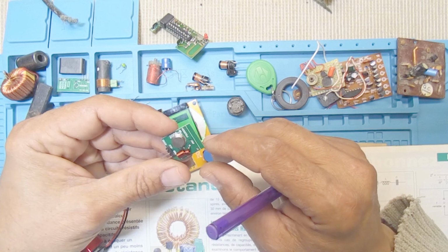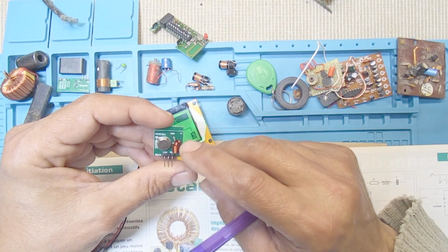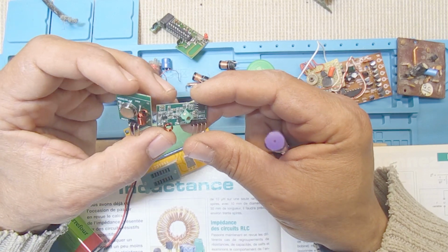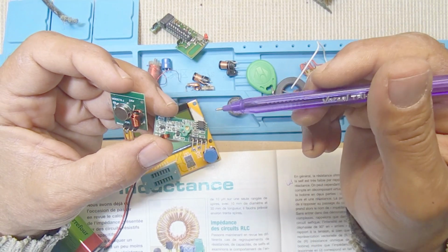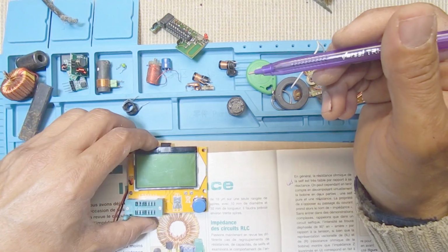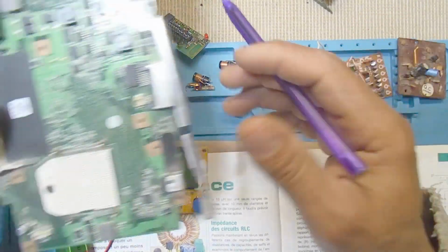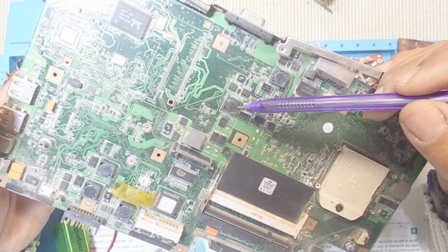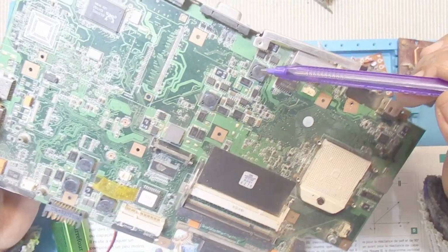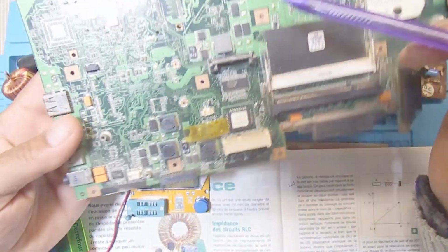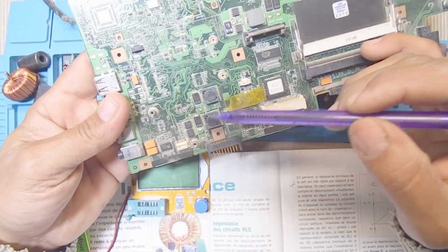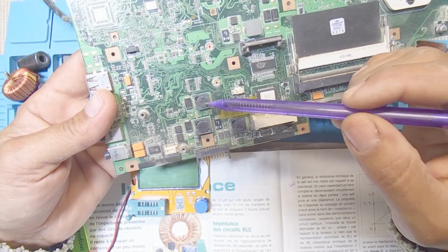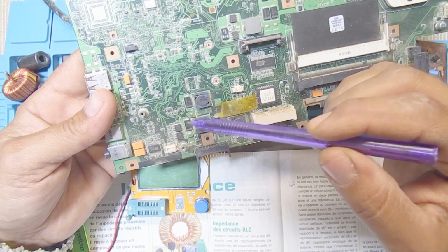Here we can find an inductor, two inductors in this transmitter, and one in this receiver. It's a variable inductor, a trimmer. And finally, we can see here those SMD inductors, they are used in the DC to DC converter. If you open a board of a laptop, we can find many of this one. SMD inductor, it's coupled with its rectifying diode here.